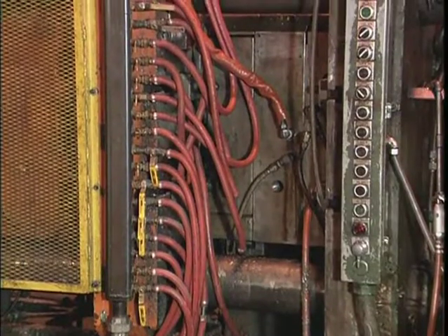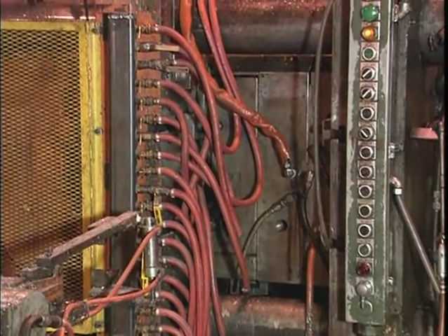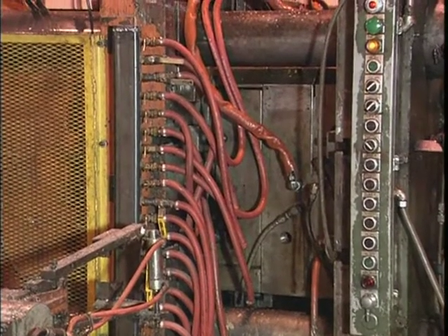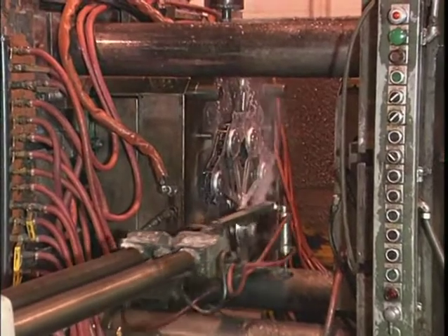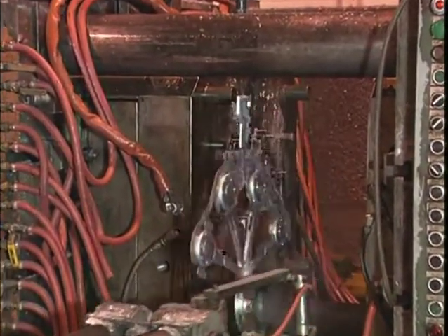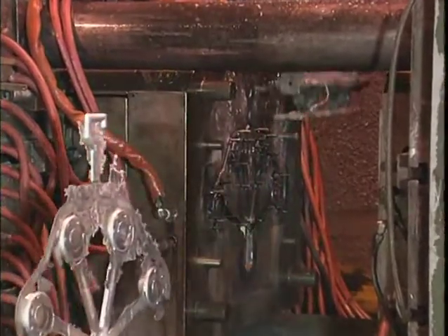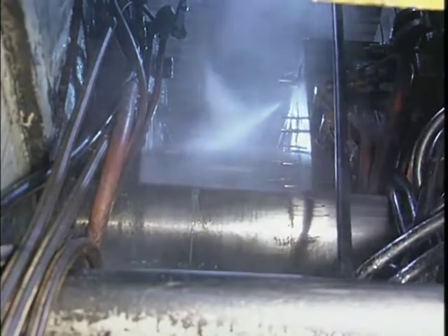Built into the die blocks are cooling lines, circulating water or oil to dissipate the heat of the molten metal at a precise rate. Cooling at a controllable coolant flow rate is important because it controls the metal solidification rate. An ejector system is required to release the casting.